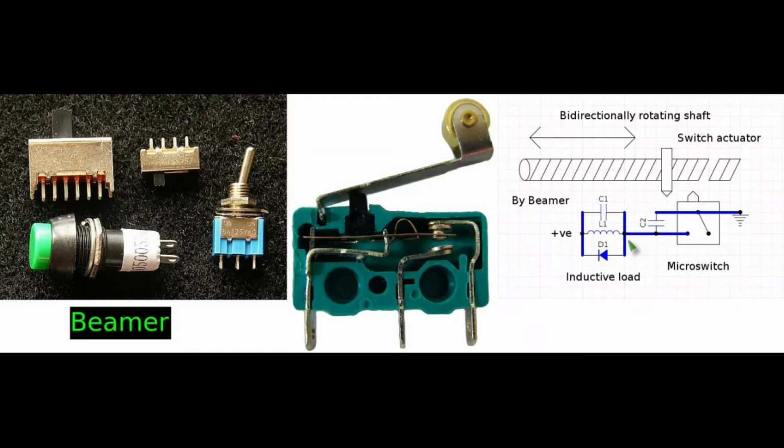Now, I can't quite remember whether this was a DC motor inductive load or a solenoid coil, but it was quite heavily inductive. The manufacturing company had installed a back EMF diode here to squash any back EMF formed when this inductor was switched off.